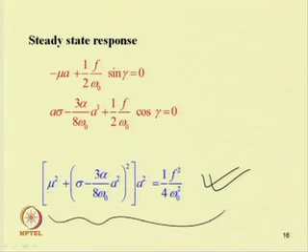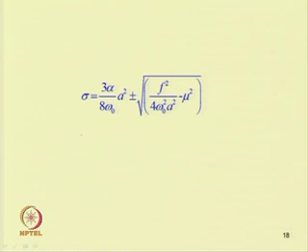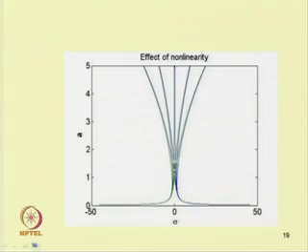In this expression, mu is the damping parameter, sigma is the detuning parameter, alpha is the coefficient of the cubic nonlinearity, omega is the natural frequency or frequency of the linear part of the system, A is the amplitude of oscillation, and F is the amplitude of the external forcing. So, using this we obtain the response equation by solving that equation. We can write sigma in terms of A, and using this equation one can study the response of the system.